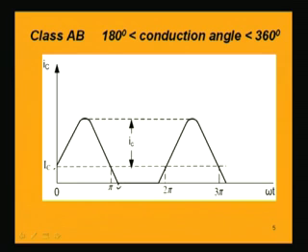So, from this point up to this point the collector current is 0. Again it will be flowing and rising, and this will continue. Because of the position of the DC quiescent point, or the DC collector current, the conduction takes place in this fashion, and that is why we get conduction up to an angle which is greater than 180 degree, but less than 360 degree.